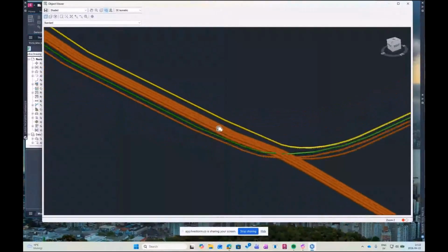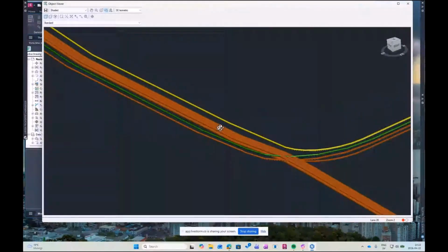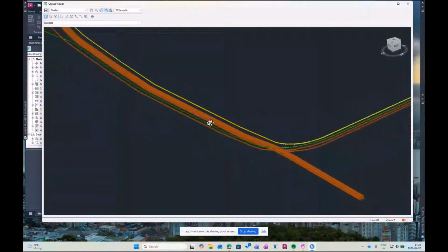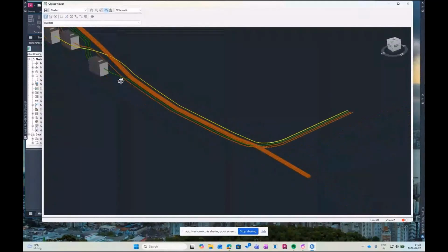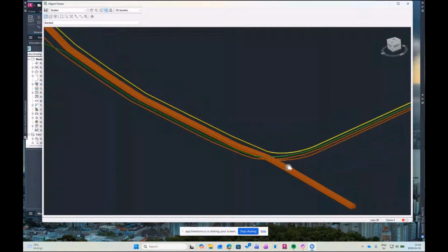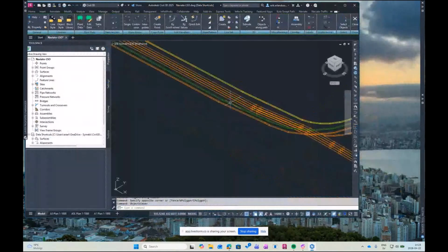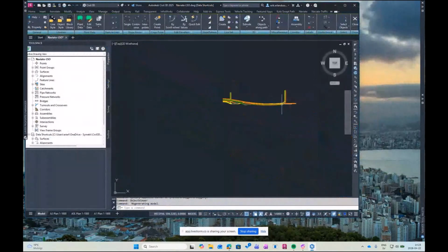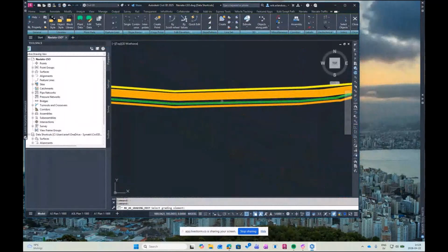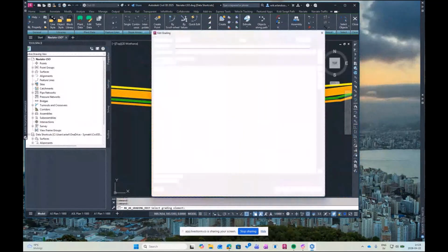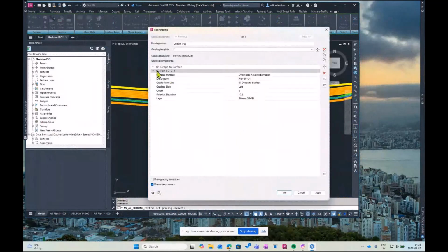The good thing with line set is that it, first of all, is dynamic, but we can also go in and edit these. So I would like to edit my green one and put it below this package of 6 pipes. So let's do that. I will go back to my top view for this. And I do edit line set, click here and select my specific line set. And I go into the pipeline, and instead of 60 centimeters below surface, I'll put it 25 centimeters more, so 85. We go OK.